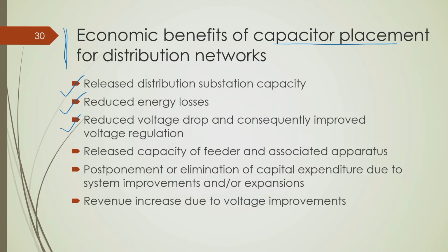I will also show you in the next part of this lecture. Also it reduces the voltage drop and consequently improves the voltage profile or voltage regulation. Also it releases the capacity of feeder and associated apparatus, and it allows deferral of capital expenditure due to upgradation or reinforcement of the system. It also increases the revenue, because power loss is reduced, and energy loss is also subsequently reduced.